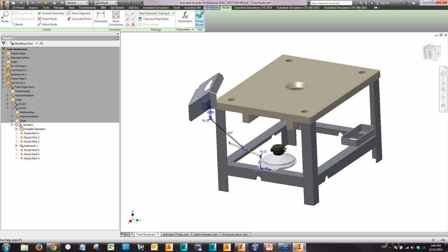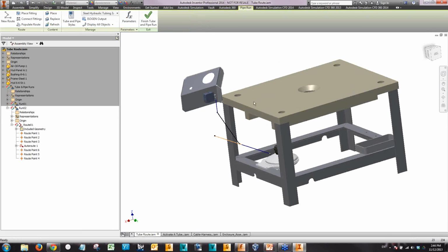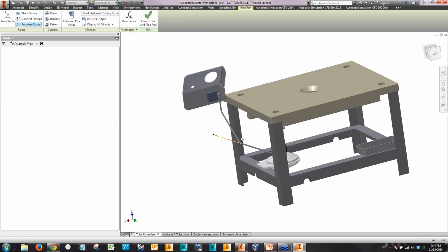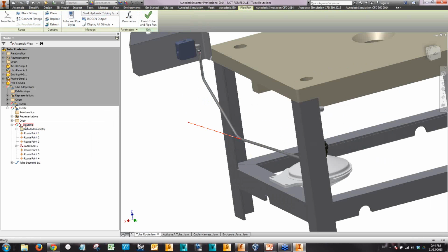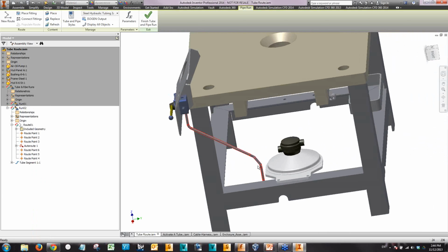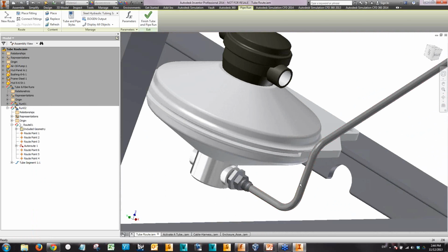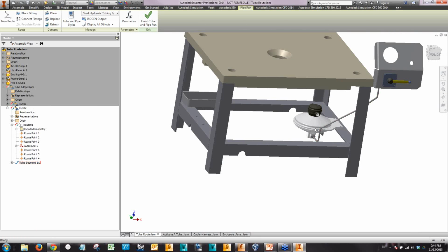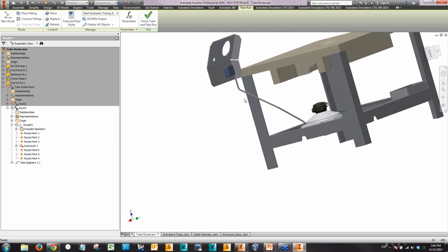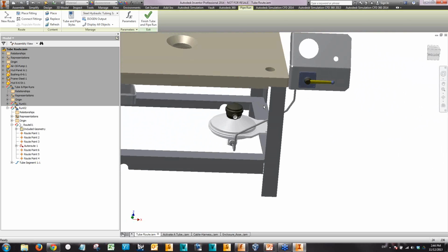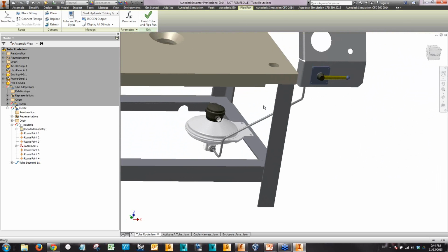So now we've our route complete. We can go on, click Finish Route. And again, we'll populate our route using our steel hydraulic tubing style. And once I turn off the visibility of the route, we'll get rid of our construction line. You can see that we've got a nice complete hydraulic tubing line routed from the valve to the pump. So there's some nice little features there like the point snap and rotation snap that we use to create that route.